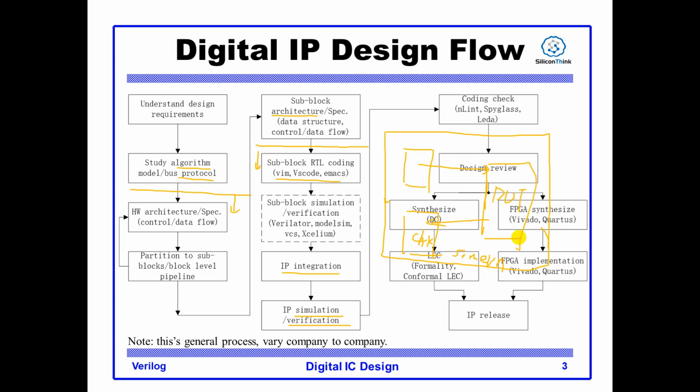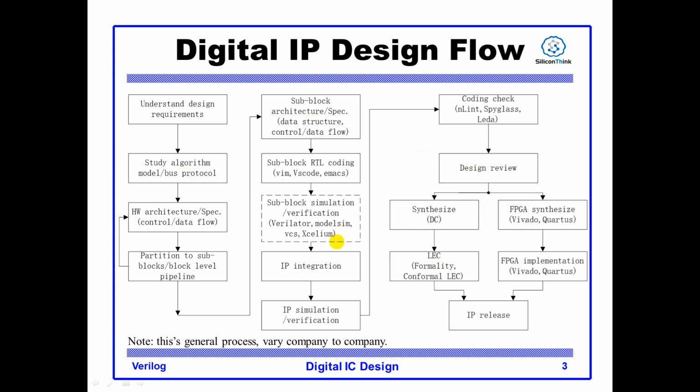result. And in this step, if you think the function of some of your sub-blocks is rather complex, and you don't have confidence about these blocks, you may choose to do sub-block simulation first. You build a simulation environment just for this sub-block. Then, after the verification of this sub-block, you will integrate it. And this block is supposed to have fewer bugs after it has been integrated.